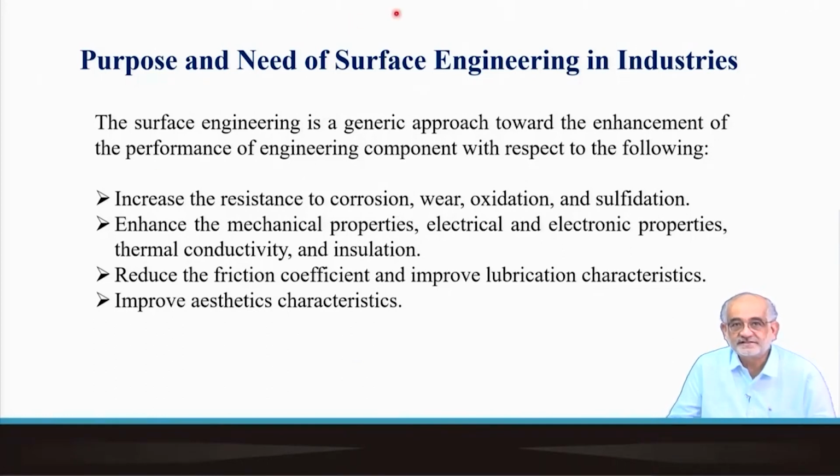So surface engineering is a generic approach towards enhancement of the performance of engineering components or solids with respect to various possible forms of degradation. It should give you resistance to corrosion, wear, abrasion, oxidation, sulfidation, or various other forms of chemical attack.